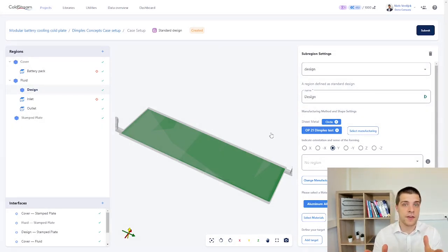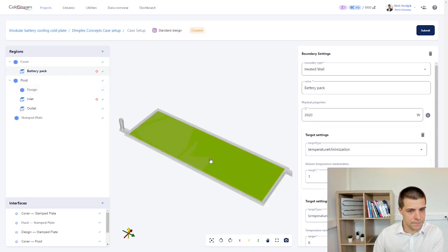So in the constant generation case, what we did here is we took one case, looked at circles, another case looked at rectangles, and then we noticed our battery pack is quite long. The incoming flow here is very cold, it hasn't heated up yet, while here towards the end, the fluid or the coolant has taken on energy, has increased in temperature. So it's very unlikely that our design, or the most optimal design, is a uniform one.